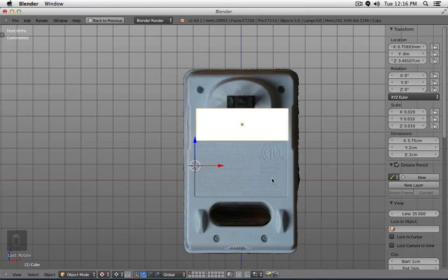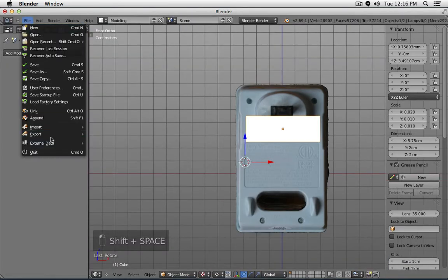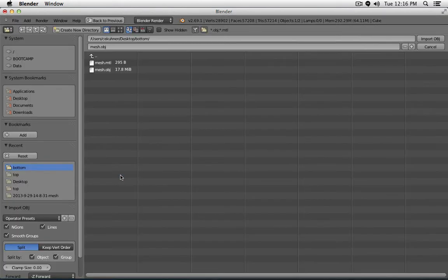the scan data, you get it with the textures, and the textures can be really, really helpful for identifying, for example, rotation or scale. And what I measured this part here on my actual piece, if you have a flat surface of your mesh, you can also write down or mark, for example, the distance of 1 inch, and then if it's a flat surface, use that as a reference for the scaling. So this is basically part 1. Now we have to bring over part 2. So for example, the top.